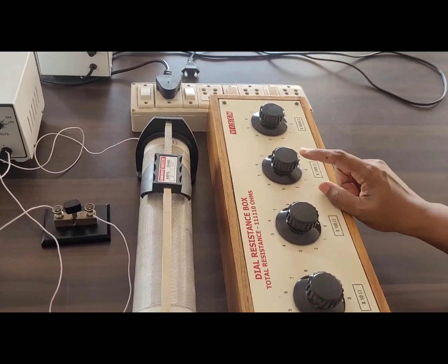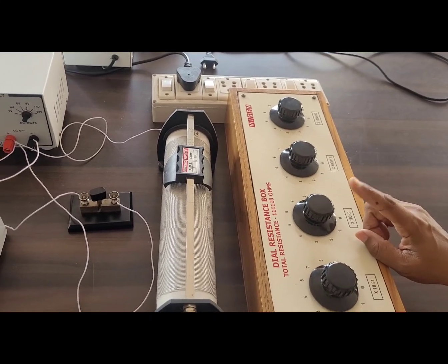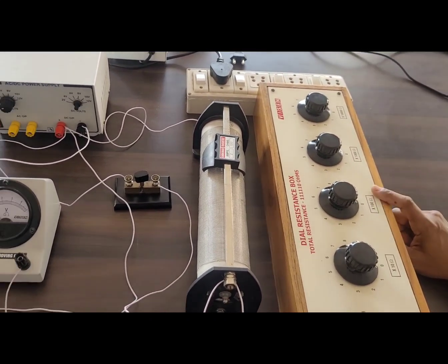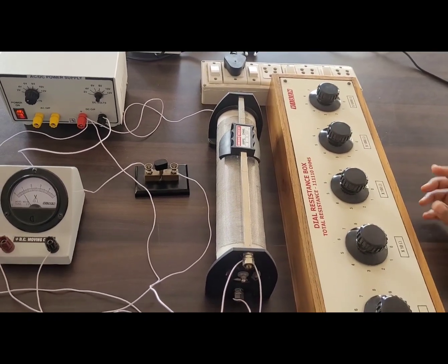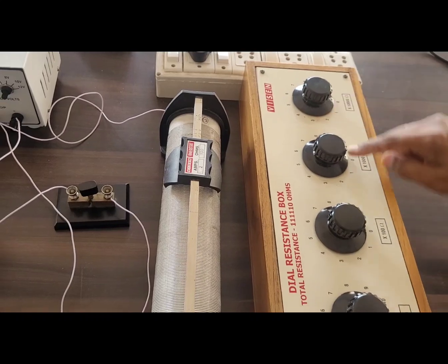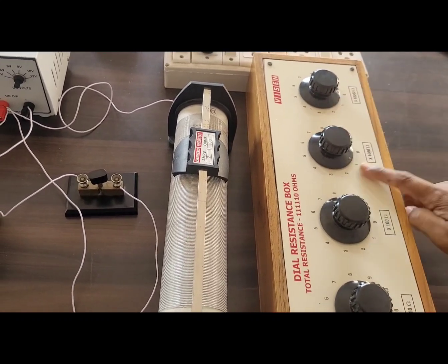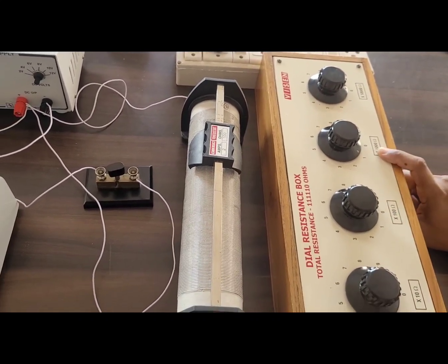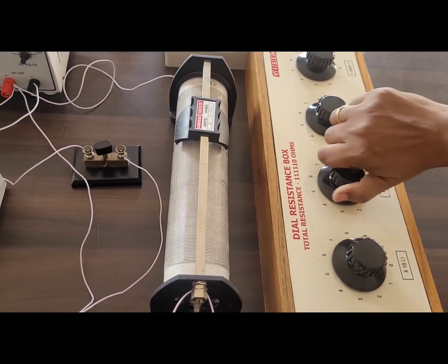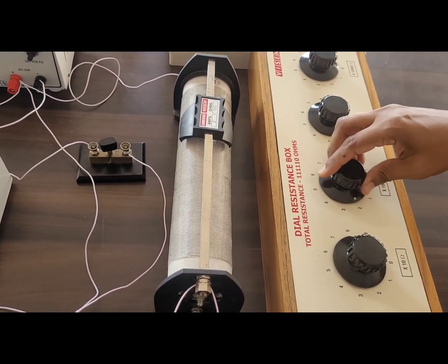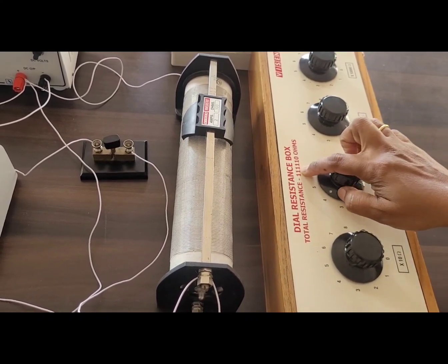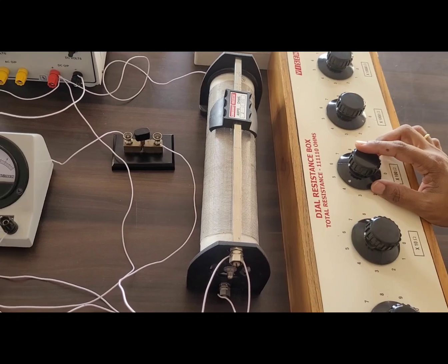We have calculated the theoretical value for 1 volt. For 1 volt the answer of R is 1566.6. Now according to that value, let us change this R value. Now it is 1000. 1 into 1000 is 1000. Now I am changing the value of 100 ohm: 100, 200, 300, 400. In this way we have to change until the needle of the galvanometer comes to the 30th division.